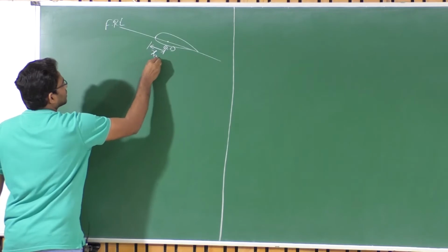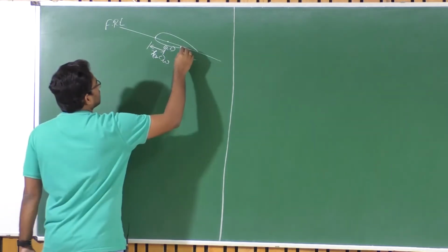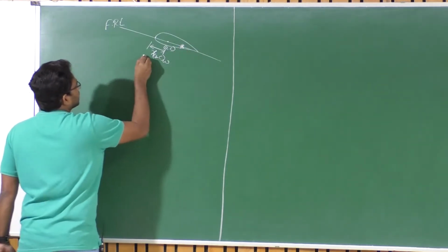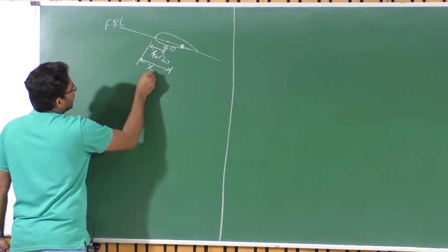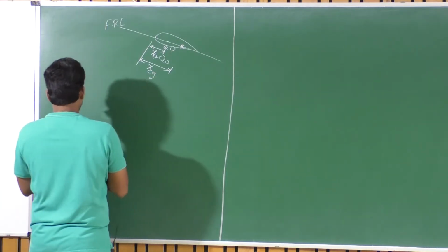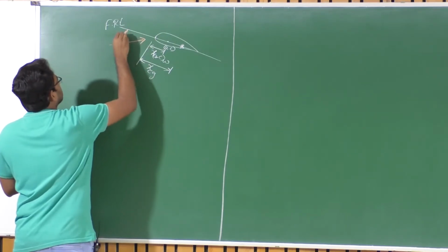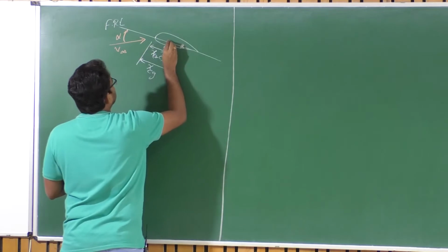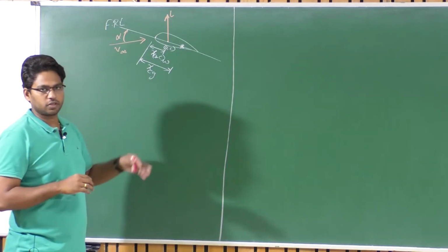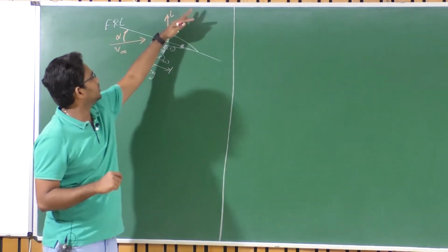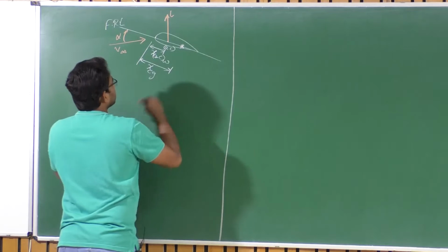So, we call this x AC of wing, right. And say the CG of the system is located at a distance x CG, again measured parallel to the fuselage reference line, of this entire aircraft. So, when there is flow V infinity, there is lift as we discussed earlier, and now we will not consider drag anymore, and we will also assume a small angle of attack so that the lift is entirely contributing towards the pitching moment about the center of gravity here. So, this is my CG,